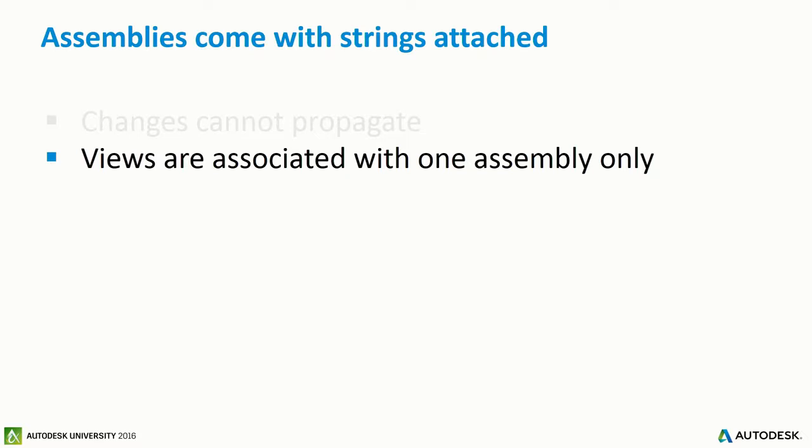it forces you to stop in the middle of whatever you were doing, go find another instance of that thing, and what they call acquire views. I thought this was insane. So I used to work for Autodesk. I used to be a Revit QA quality assurance analyst. And so when we were developing this feature, I went, why are we doing this? This is crazy. So you'd have to find another instance of that assembly and acquire views, which would mean it would take those views from the one that you want to change and relocate them, reassociate them with a different instance of that assembly. I don't have an explanation for it. I don't know why. It just is. I didn't understand it when we were designing it either, so it's a little bit unique.